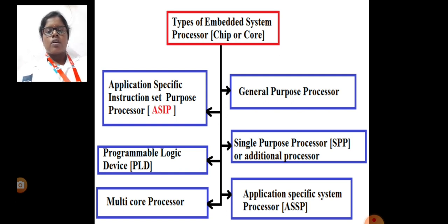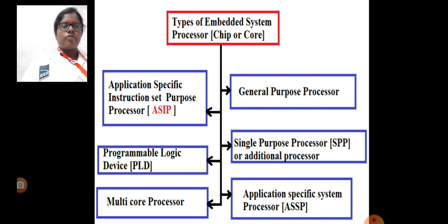In a microprocessor, the CPU unit generally fetches and processes a set of general purpose instructions. It has the following instruction sets. In 2 marks they may ask what the instruction sets for a microprocessor are. First one is instructions for data transfer operations. Second one is instructions for ALU operations. Third one is stack operation instructions, and fourth one is input and output operation instructions. Fifth one is program control instructions, and sixth one is sequencing and supervising operation instructions.